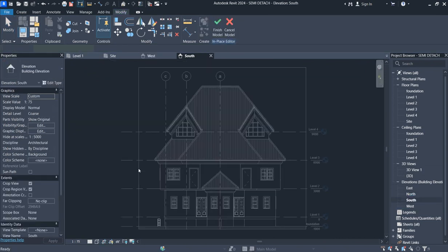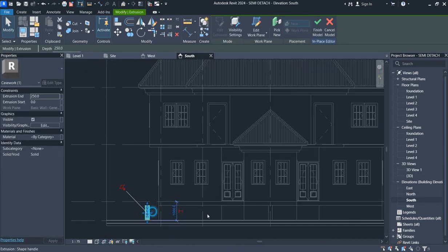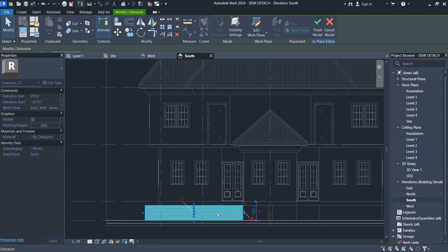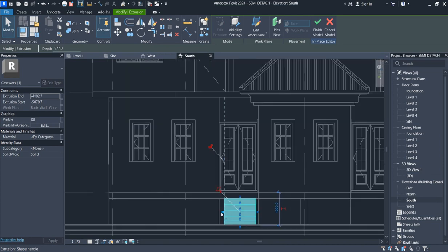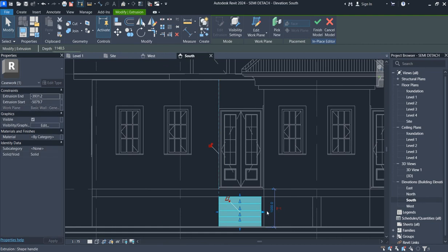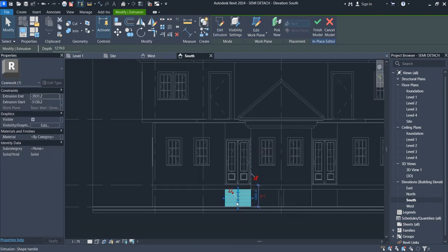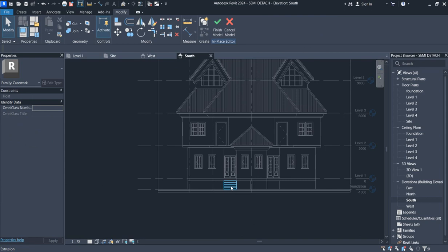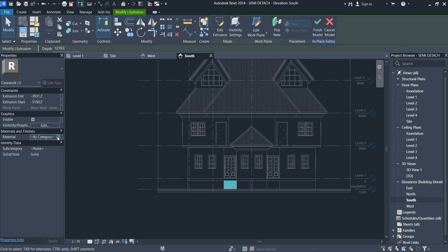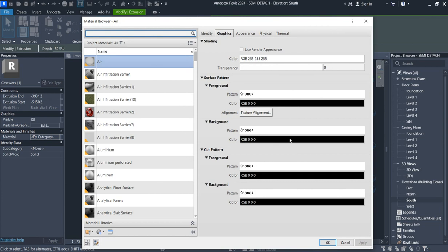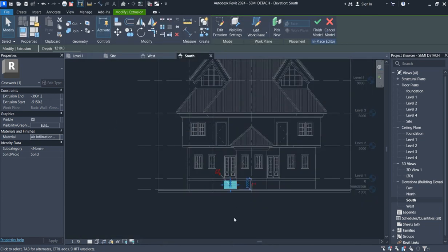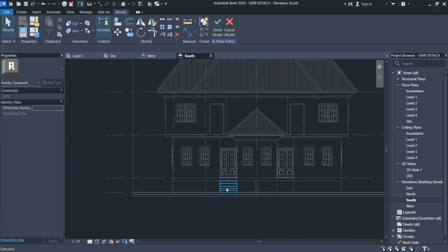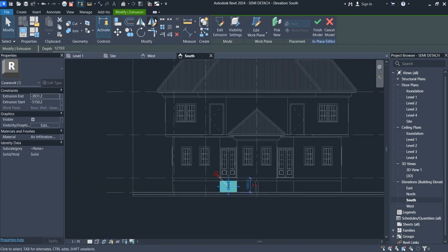So you go to front elevation. From here you adjust the whole process and bring it to the position. So now drag this. Good. So as you are done with this, you can now decide to select material for everything. So here you select material category. Material category, you can decide to choose whichever suits you, and I want to use this particular one. So that one is there. When you do that, now you can mirror.